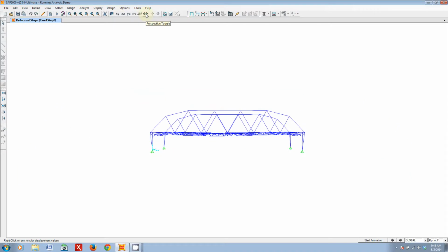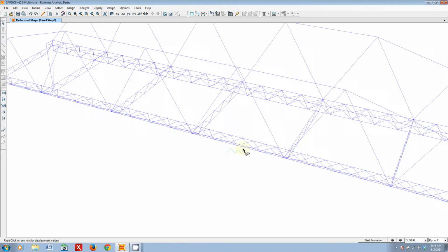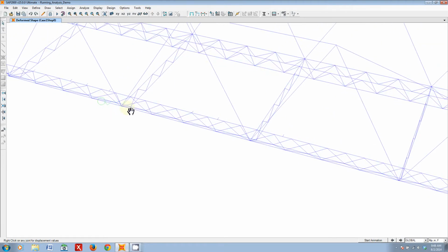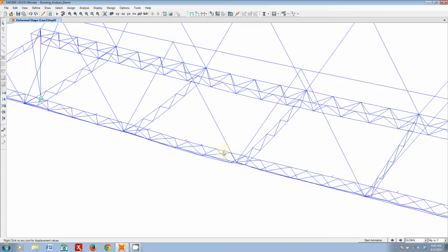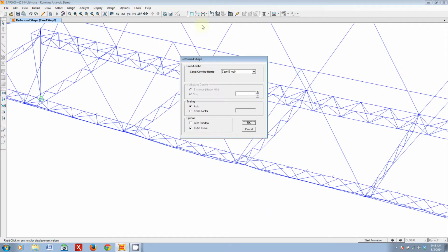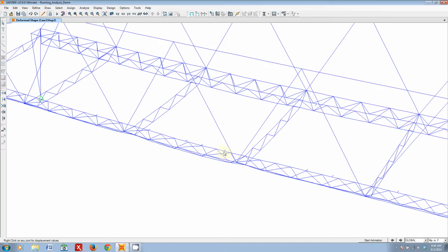What can we do with that? Well, you can go to one of your deflection points, and the nice thing about having your points named is that when you hover over them, you can see this is the point corresponding to the load location for case 1, deflection point 1. And we can measure directly what U3 should be, which is negative 0.0225 inches. So that would be the value that you would pluck off and use, more or less. But remember, this is the preload case. So you'd have to go through and check out the actual final deflections at step 2 for case 1, which ends up being something like negative 0.229.